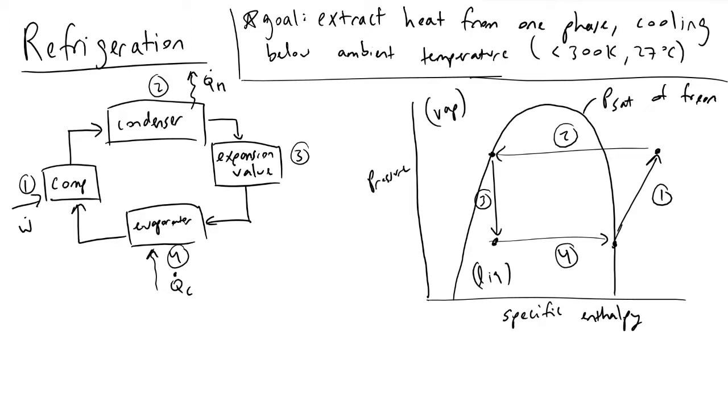And so because it is a continuous loop, it really doesn't matter where you start in this process, but I'm going to call compressor point 1. And so at point 1, what we see occurring in our pressure versus specific enthalpy plot is the pressure is increasing. And that makes intuitive sense because the point of a compressor is to compress the fluid to raise the pressure. But we also see that the enthalpy, I'll call it delta H, is also increasing. And so your compressor has taken the Freon vapor and raised its pressure.